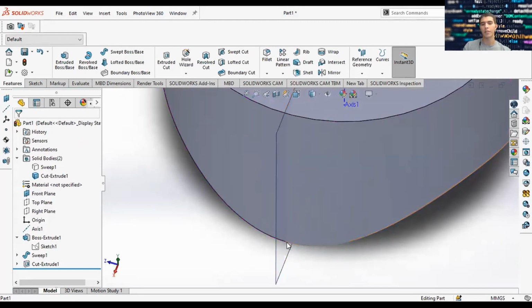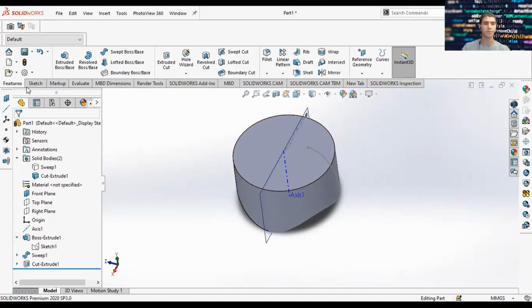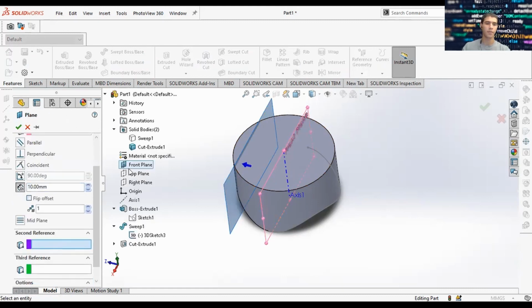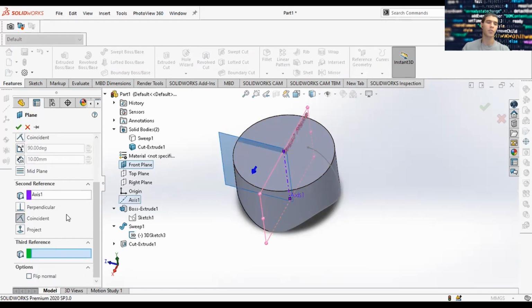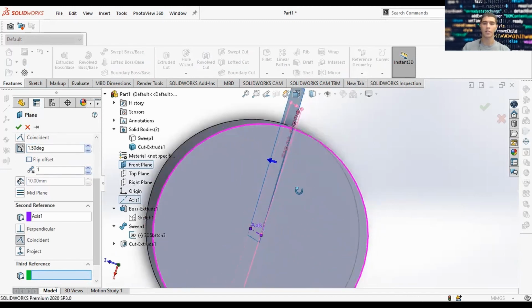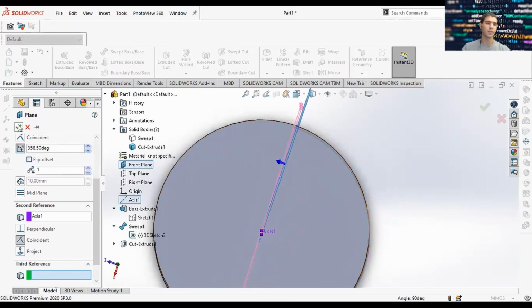So now this front plane is going to intersect this curve-driven function at that point. So that's good. What we want to do is create a geometry that is offset from that at an angle. So this is where the axis comes in. We declare the front plane, and then we declare our axis, and then we just find the appropriate angle for it. In particular, we want it to be 1.5 degrees off from the axis. So it should be 360 minus 1.5, 358. Yeah, that's fine.